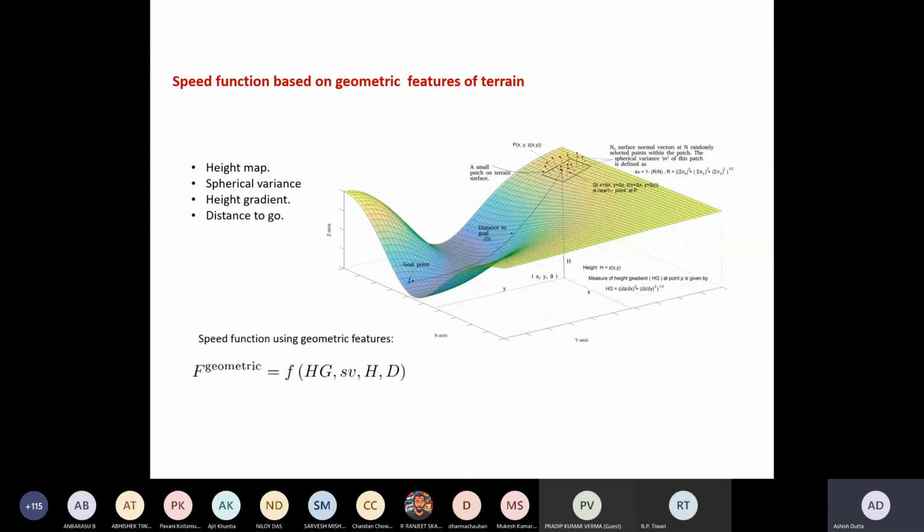So what we did is we incorporated the dynamics of biped walk along with the terrain geometry. The terrain geometry is being included by looking at the height of the terrain. Okay, so corresponding to here, this is higher. Now it has normals, so these normals are making angles. So we're looking at those angles.